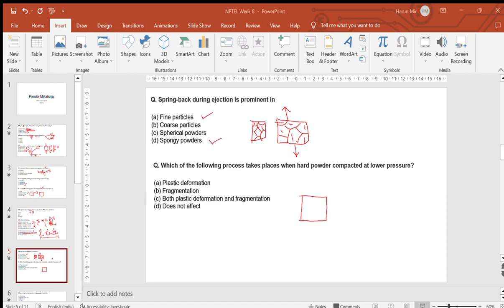Because the pressure is the same for both cases and the viscosity is the same for both cases, we have something like this: pi d raised to power 4 divided by 128 L, and we have W, which is the width, times thickness cube divided by L. So we can just rearrange it first.